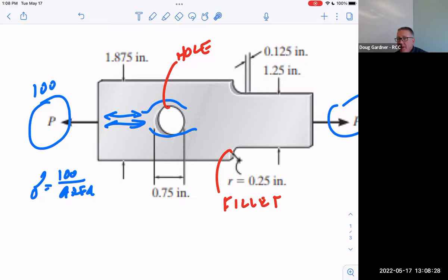Well, do you see the same thing happening there? If you think of the same thing I was discussing, kind of the idea of flow. If I've got the force coming here, isn't that force going to have to kind of turn and work its way down here? So essentially, isn't there going to be a concentration right there? Notice these forces don't know anything changed, right? But all of these forces up here, they're going to have to all flow together and concentrate. So stress concentration, there's going to be concentrations where a shape necks down like that to something smaller, or if there's a hole in the way. You see the basic logic to that?